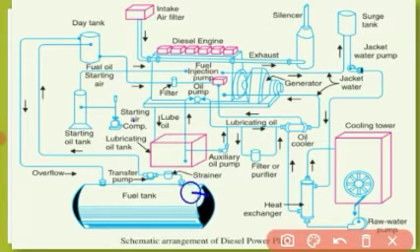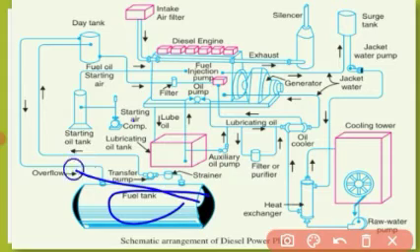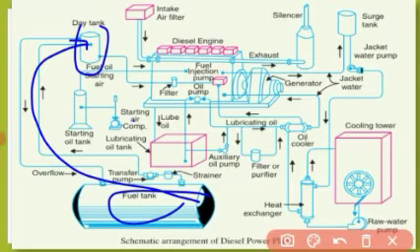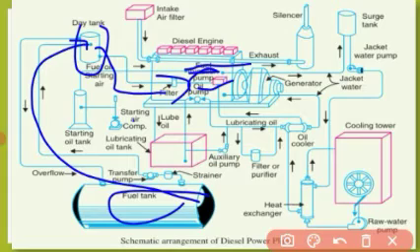Fuel diesel is stored, then taken to the day tank, a small tank for one day's use, and from there it is given to the fuel injection pump.